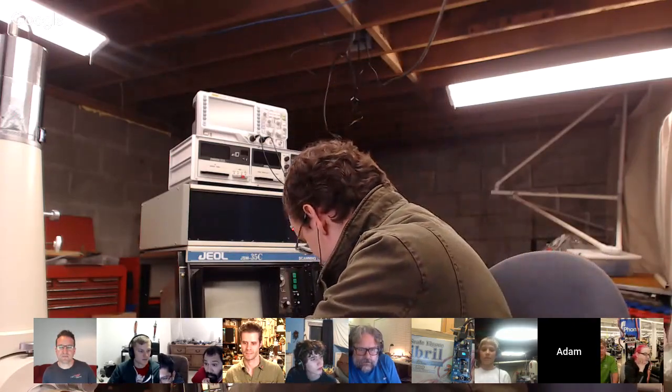So I borrowed this amazing piece of kit. This is called an RGA, or a Residual Gas Analyzer, and it's basically a small mass spectrometer, and it can detect what type of gas is inside of the scan column at vacuum. So it can look at basically individual atoms and count them. What we can do with that is hook this up to the controller and my oscilloscope. And there's a test port on the back of the stem there. So set that thing in there.